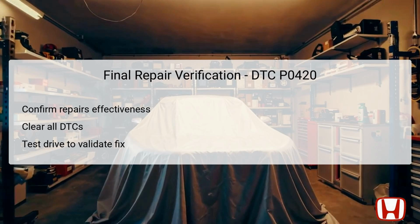Start by clearing all DTCs from the vehicle's computer using the HDS, ensuring that the prior errors no longer populate the diagnostic menu. Following this, conduct a thorough test drive in conditions similar to those that previously triggered the trouble code. Monitor the vehicle's performance and the HDS diagnostics for any reappearance of the P0420 code or any related errors.